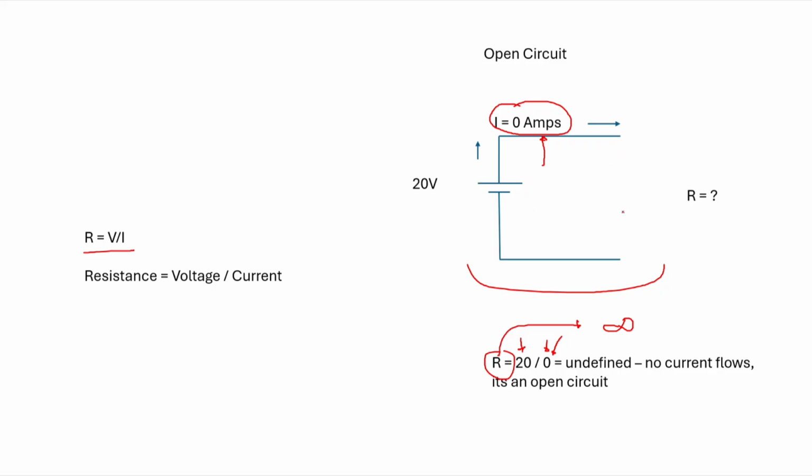Right now, current's not going to flow, but what happens if I increase this voltage to some hellacious number, like 30,000 volts? At some point between this terminal and that terminal, depending on how close they are, you're going to get arcing or a spark.